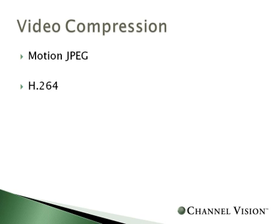We talked a little bit about video compression earlier, including Motion JPEG, H.264, and MPEG-4. Motion JPEG is, just as implied, a stream of individual snapshots. Motion JPEG is often used for lightweight devices such as cell phones and touchscreen automations because it is a little bit lower resolution. Today, one of the better options that you can utilize is H.264 compression, which is better quality and less space.